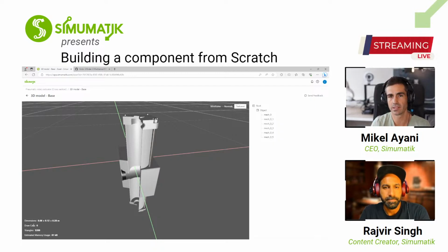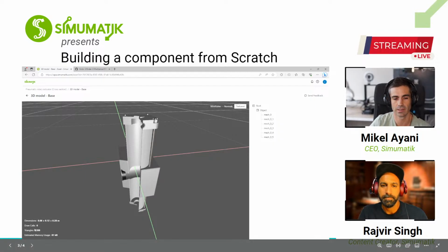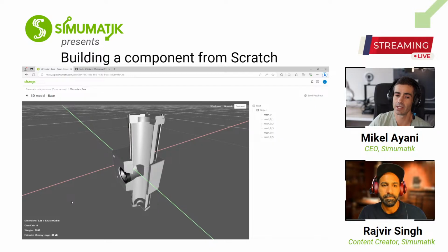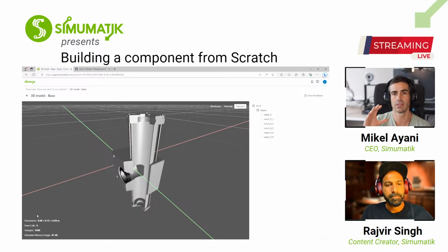Okay, in this case, it is 6 calls to the graphic card to visualize this 3D model, and then the complexity in numbers of triangles. Okay, so we could say that the number of triangles is less important than the draw calls. You need to try to minimize the draw calls to the GPU or the graphic card in your models.